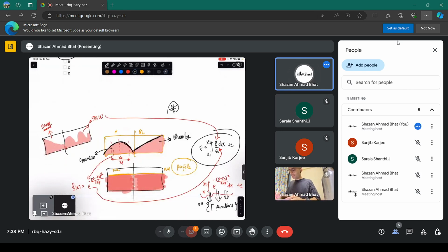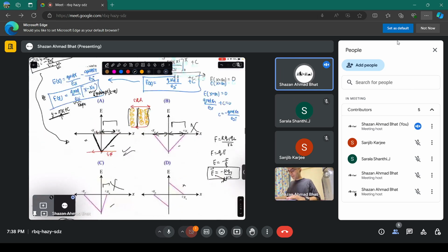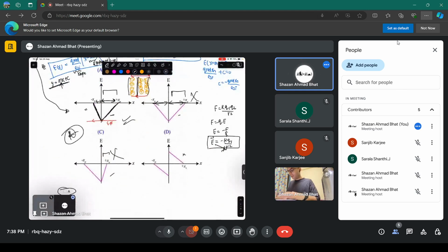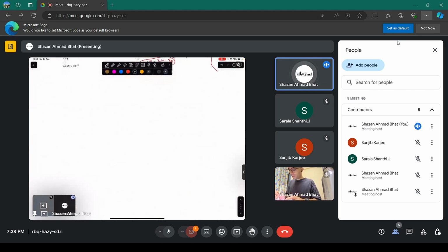This is the important part. I will continuously highlight it because it requires some sort of calculation at least, and developing these band diagrams is very essential. How you go from a charge profile, this is a space charge region, to a region where you make the rho of x, which is the charge density, q times nd minus q times na.